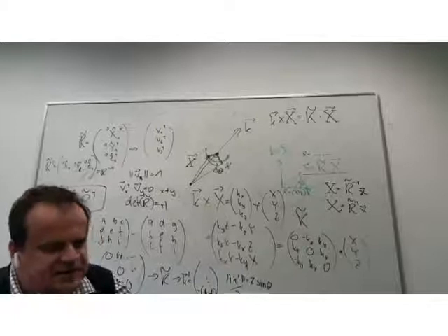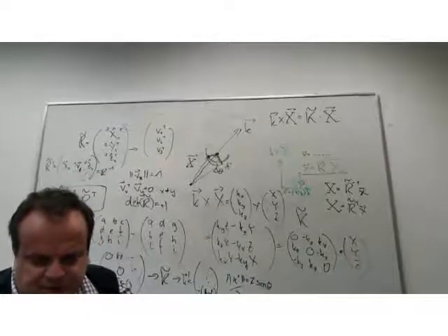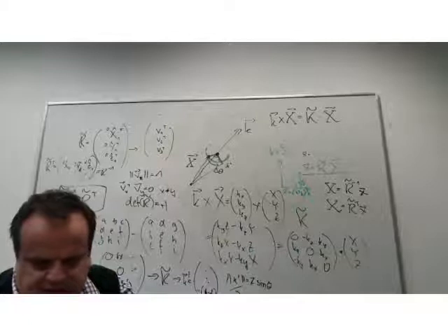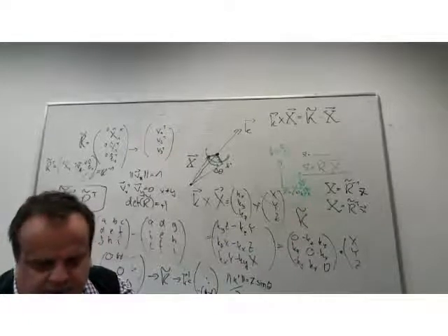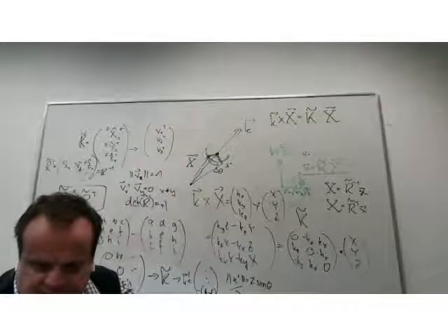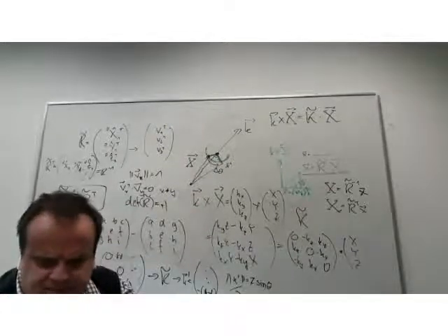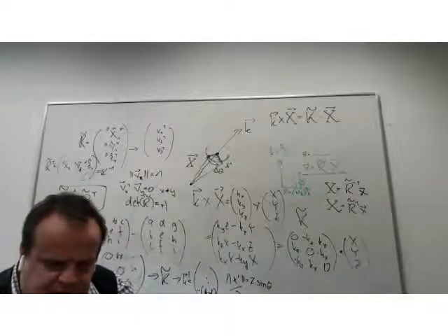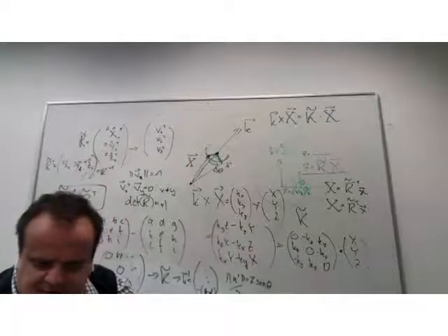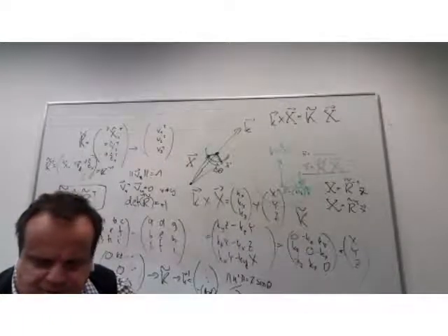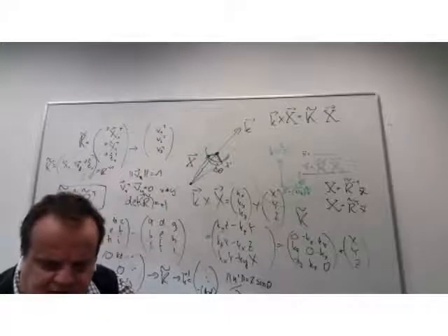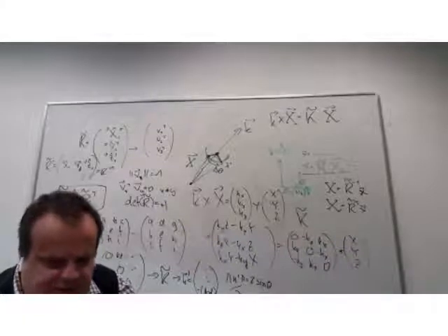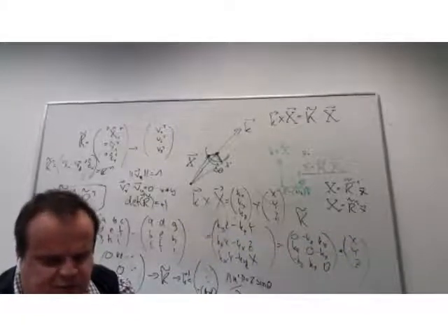For axis angle, it's difficult. That's why people use quaternions. And you see that there is a natural relation between quaternions and this axis angle representation. The quaternion has 4 elements. The first element is just cosine of the half of the angle of rotation. The second element is the x component of the rotation axis times sine of the half of the angle, then y times sine of the half of the angle, and z. So a similar representation to what we just derived.